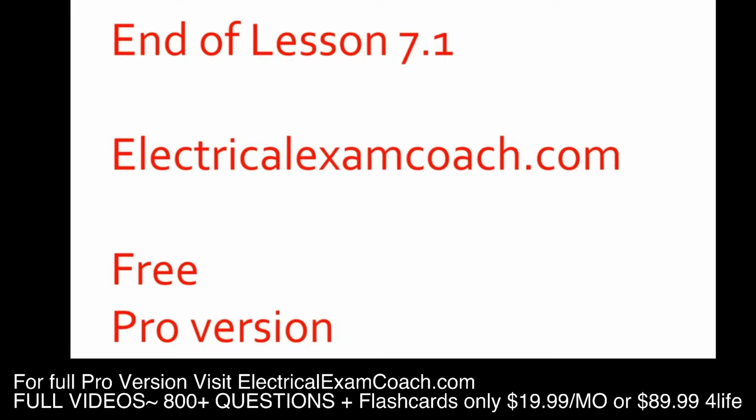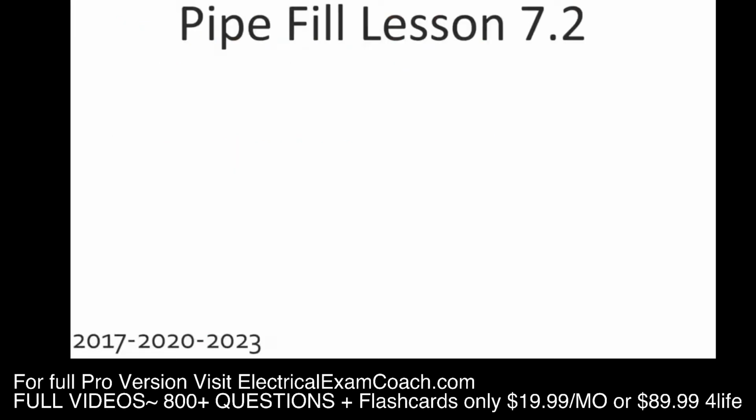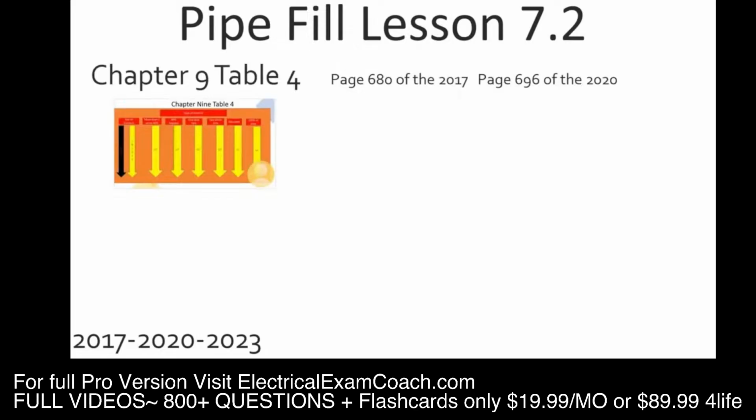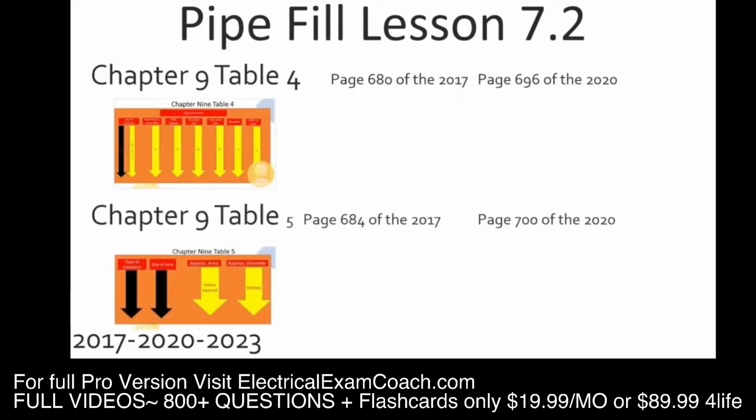Let's get to it. Hey everyone, welcome back. I am the Electrical Code Coach, and we're picking right up in pipe fill. This is lesson 7.2. In our previous video, we learned that if the conductors are all of the same size and insulation type, we can just head straight to NEC to answer all of our pipe fill questions. But when they're not, we're going to learn about what to do today. We're going to learn about Chapter 9, Table 4 and Chapter 9, Table 5.